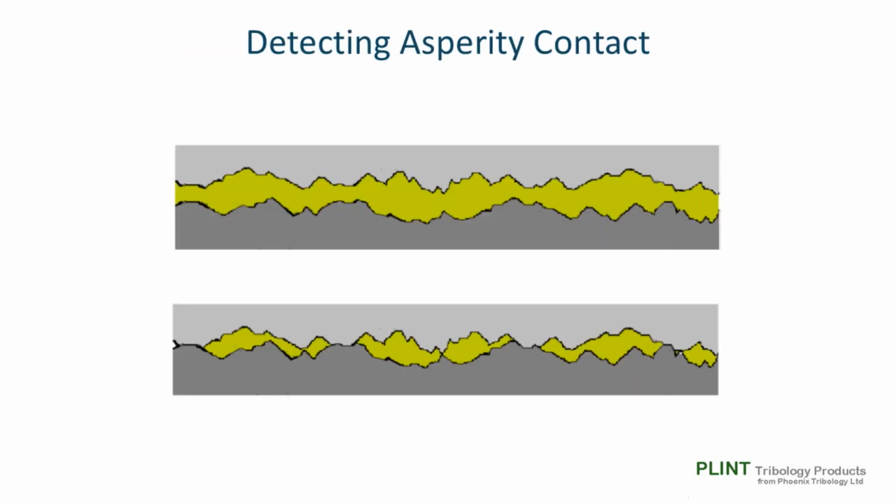If we have two surfaces separated by a thick non-conducting lubricant film, we effectively have an open circuit switch, so nominally an infinite resistance. A contact resistance signal will thus be the open circuit voltage of the system. If the fluid is a mineral oil, it will have very high electrical resistance.